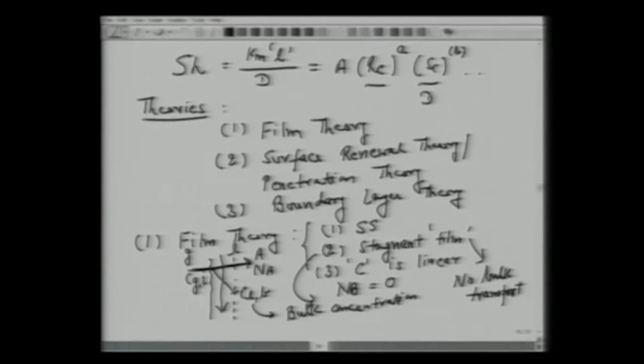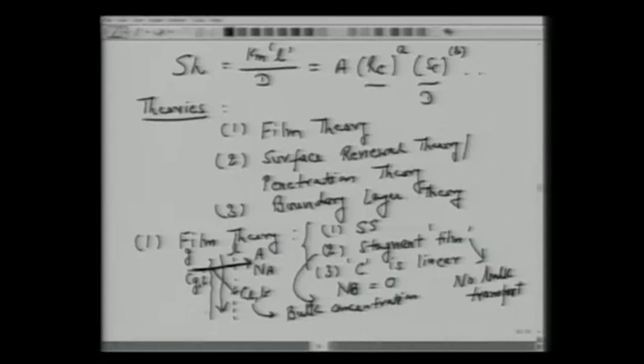It means the concentration gradient from CGI to CLB is linear and does not change with time, and there is a hypothetical stagnant film in which we assume there is a diffusion resistance, or a diffusion length del Z, over which the concentration drops linearly from CGI to CL.